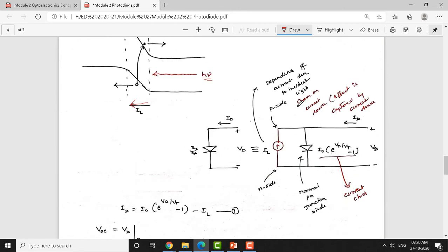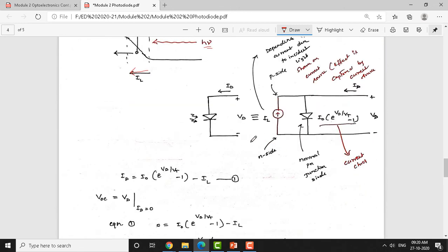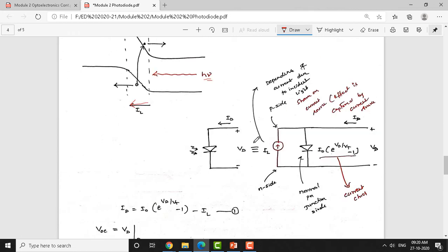And now, let us write the equivalent circuit of the solar cell, and later we will explain the mechanism of how we can extract maximum energy from the solar cell. So, this is the symbolic representation of a solar cell, that is a diode. It is nothing but a diode with this arrow mark that shows a solar cell. In order to draw an equivalent circuit, first you can write this without the arrow mark, treating it as an ordinary junction diode.